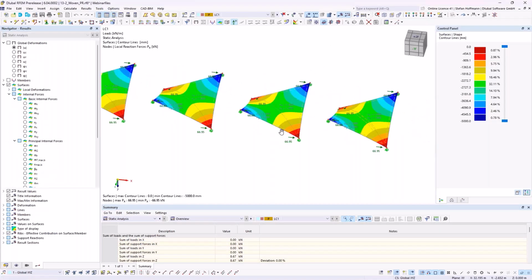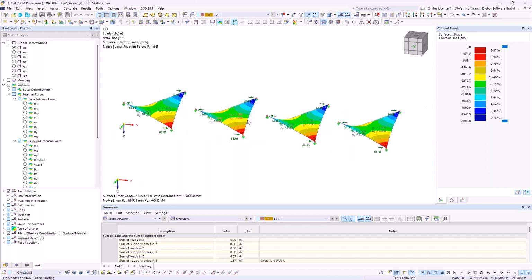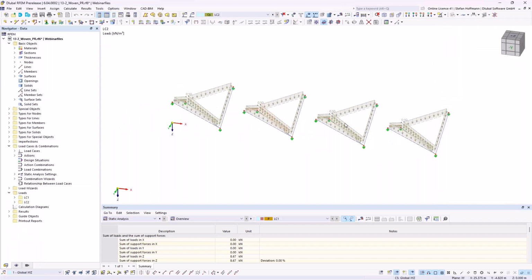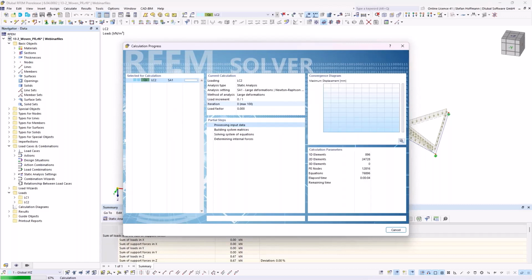But still, as told, we receive the same results for our form finding process because the boundary conditions are the same. And due to the fact that we define the prestress, we will receive in this state the same shape. If we now apply a load to our form found structure, all the material properties and also the boundary conditions, etc. come into play.